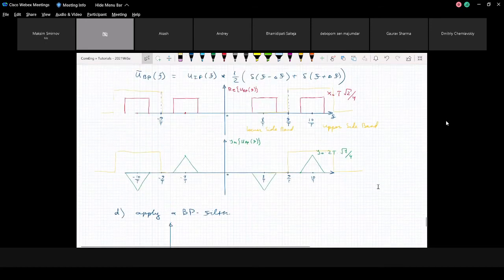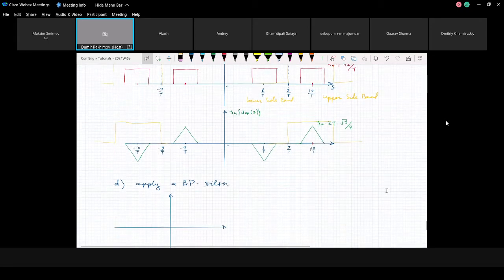And also we perform the transformation with respect to frequency 10 over T. So again, we remove the negative part, we shift our signal to the left, and we normalize it by multiplying by square root of 2. As a result, we get a rectangular shape window, a spectrum at frequency 0. The spectrum goes from minus 1 over T to 1 over T.